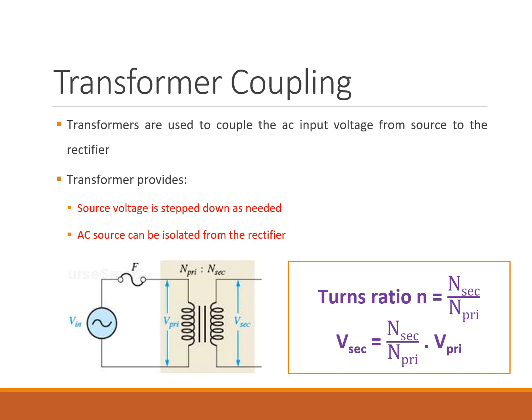So for example, let's say you had 120 volts coming in. Let's say you had a 10-to-1 step down. So you had 10 turns on the primary for every 1 turn on the secondary. So we're dropping it down by 10-to-1. And so that means on the secondary, we would get 12 volts AC out. Right? And so that seems a whole lot better, instead of 120 all the way down to 12 to feed a diode, so you won't burn out a diode.